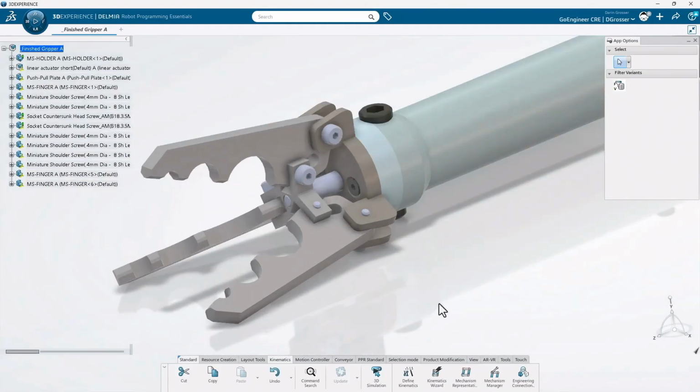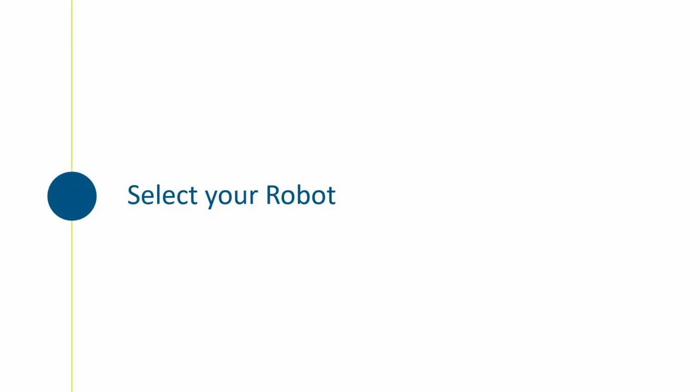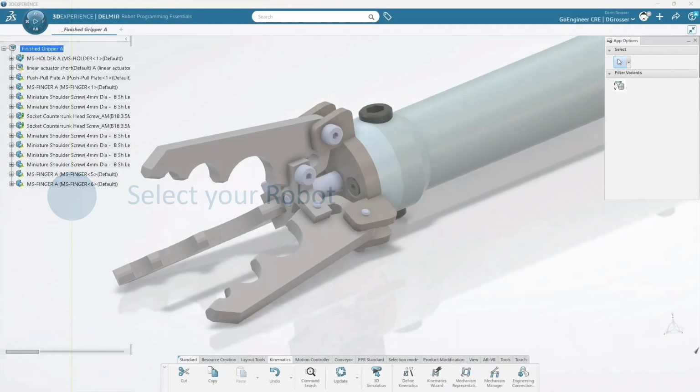So in this case, you build end-of-arm tooling that's completely custom, and through a few simple operations, we're really just doing what we do in SolidWorks, grabbing a few key features here, adding revolute joints, adding hinge joints, adding the things that you need. Now, that's as far as the SolidWorks stuff goes, or any CAD data, frankly. You bring it in, it's neutral, it's a nice structure of hierarchy and a subassembly, but it still needs that mechanistic part of it added. But again, that's a flexibility that's really cool.